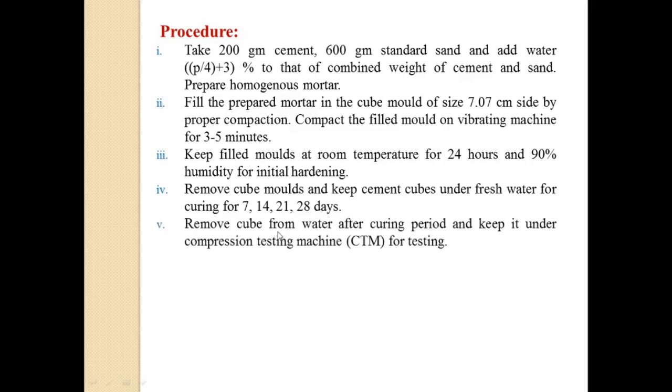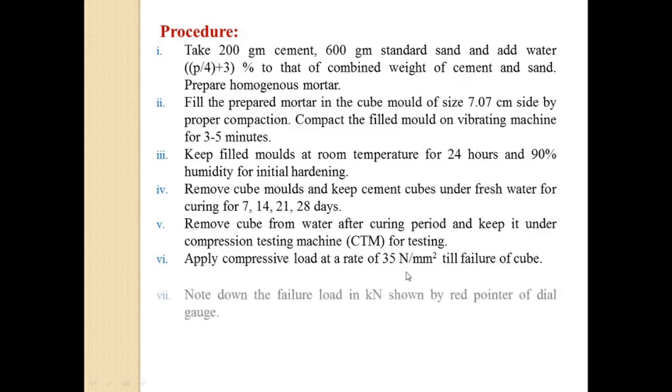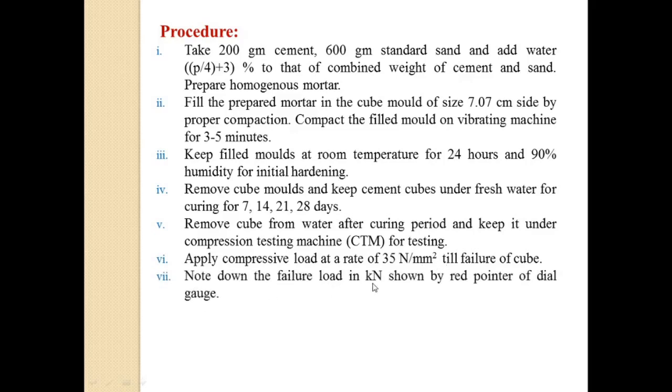Then remove the cube from the water after the curing period and keep it under the compression testing machine, that is CTM, for testing. So apply the compressive load at the rate of 35 Newton per mm square till the failure of the cube, and note down the failure load in kilonewton, which is shown by the red pointer of the dial gauge.